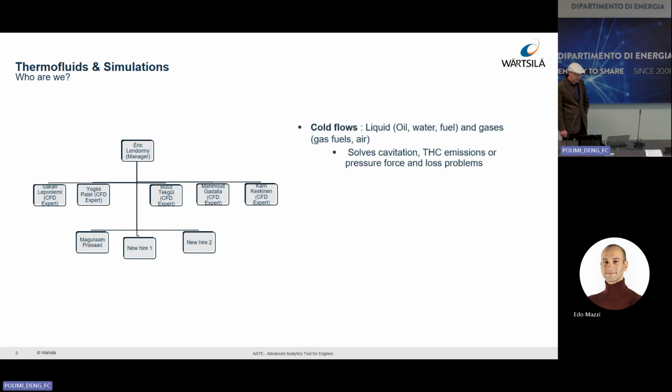What we do there is some cold flows, obviously, because we don't just simulate the engine combustion, we actually do the whole parts of the engine. So we start with cold flow, liquid or air, like turbocharger optimizations for air ducts, charger coolers, oil and water and fuel flows.